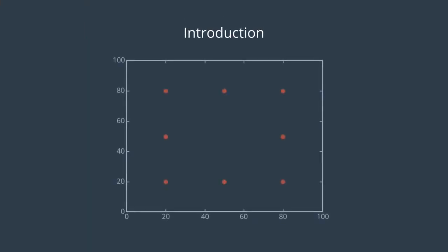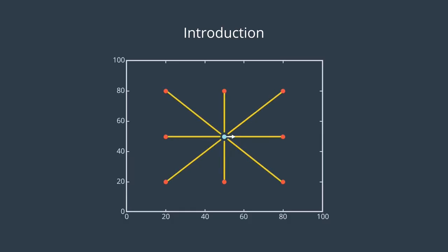In this lesson, you will code the Monte Carlo localization algorithm in C++. Before we start, let's take a look at the problem in hand. Inside this two-dimensional map, a mobile robot represented by a blue color lives in a world of size 100 by 100. This robot can rotate left or right and move forward. The robot can also measure its distance to the 8 landmarks represented in red using a rangefinder sensor.